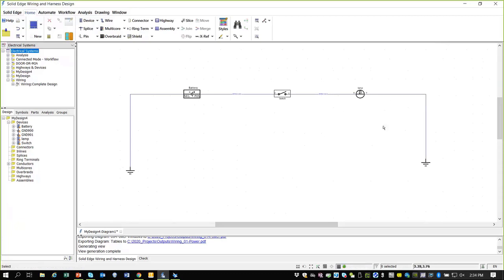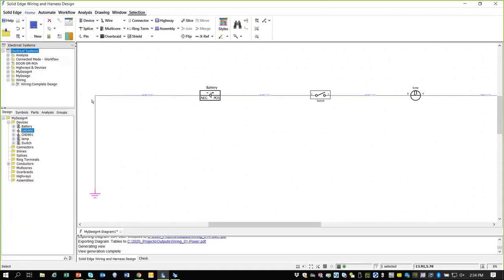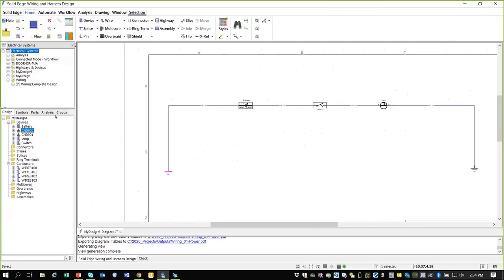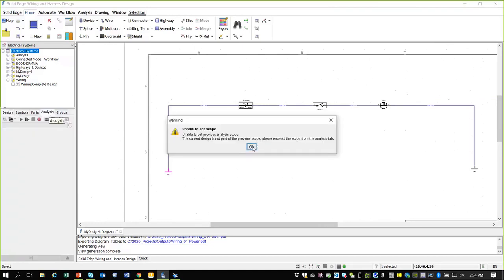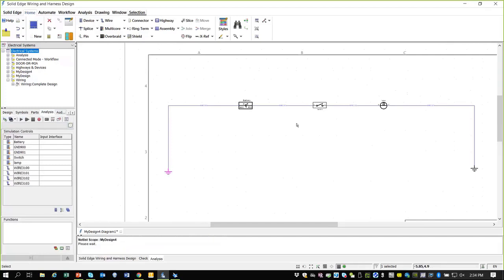It knows what a wire is and how it needs to behave. And we see the names on all the wires, right? It's following some styling section that says don't put the wire name there unless it exceeds a certain length, so that's what it's doing. And then we look under the conductors here, and here's where we see our wires. And when we put down a wire, it's using the default properties of the wire there. So with this down, I'm really ready to simulate. I can hit my analysis and then start the simulation.